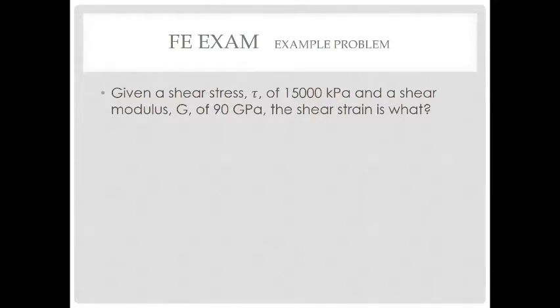I basically rounded that to 0.002 newtons per meter squared. So we calculate shear strain, right? So you should not have units. Oh yeah, that's right, no units. All right, so the answer is, in fact, 1.67 times 10 to the minus 4. Therefore, your rounded number would be correct.